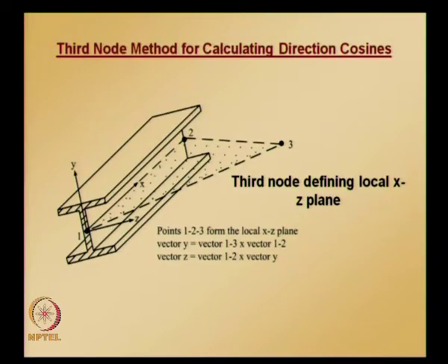And so, the assembly and solution procedure for nodal degrees of freedom is the standard procedure which we are following till now. After a nodal solution is obtained, the displacements, axial forces, moments and shear at any point along the 3D frame element can be computed using shape functions and its derivatives, as we are doing for the plane frame or trusses or beams that we have seen till now.